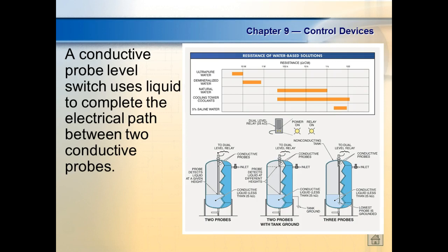We have what we call capacitive sensors, which the current does not flow through them, but we can control the amount of current flowing in and out. So the fuel level sensors that we had on our airplanes were capacitive. It was just two tubes, one mounted inside the other, which formed the capacitor, and when the jet fuel got up in it, it would give us an indication.